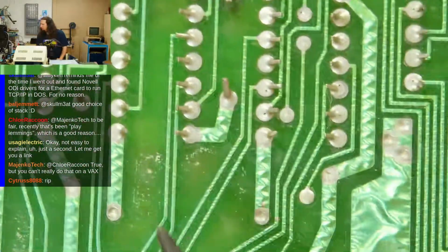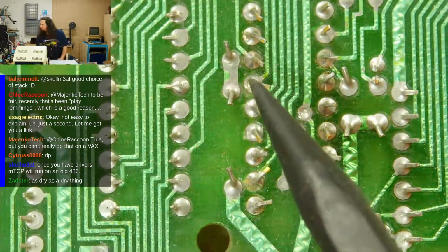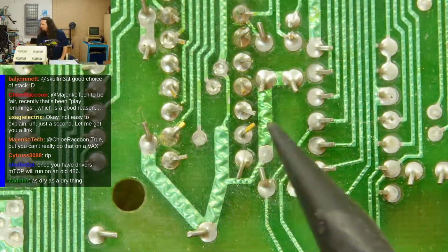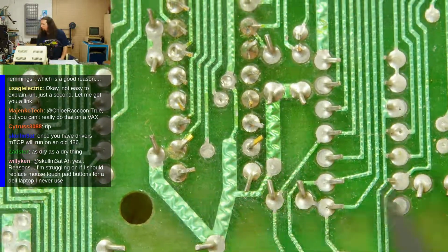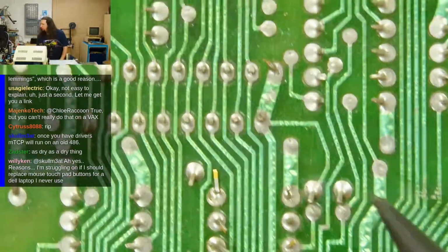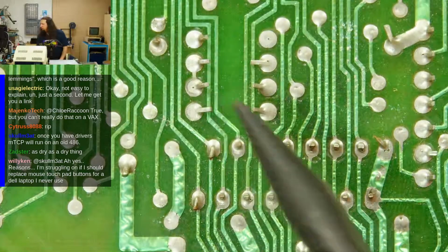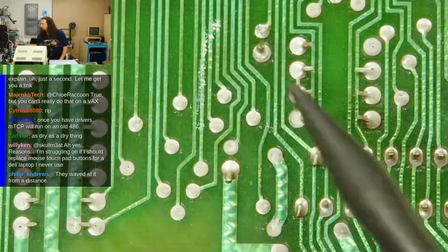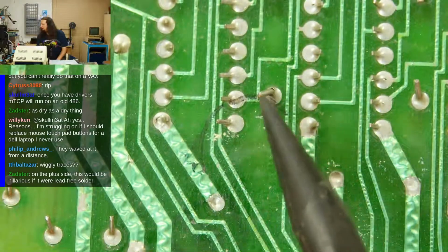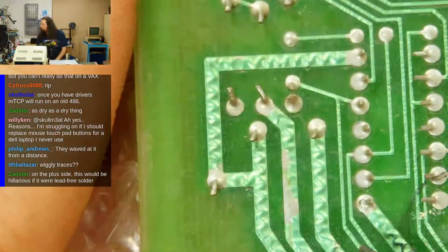Over here, I saw a pin where DG just kind of sneezed a little bit of solder at this one, and then they kind of called that good enough. These ones, they barely soldered so much, didn't even wick all the way up the pins. That one looks pretty rough. That one, I don't like that one. Okay. That one really bugs me a whole lot.